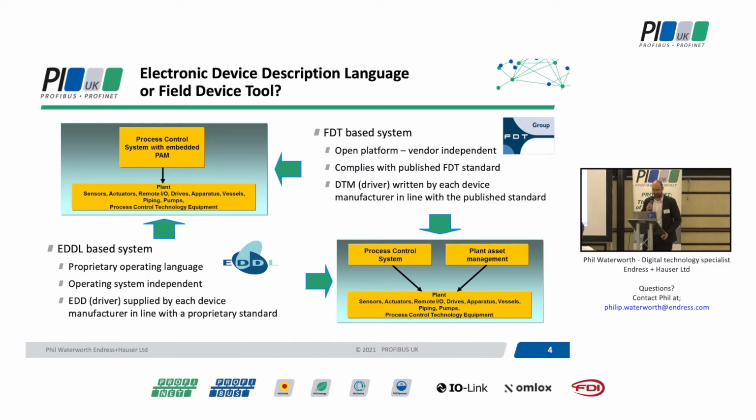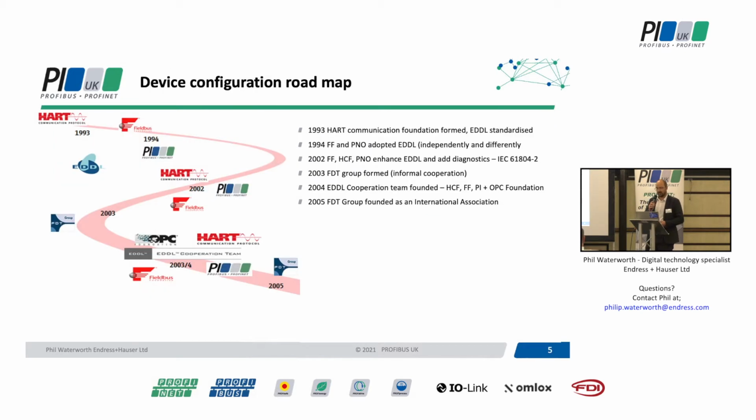So it can actually reside within your control system package that you have, or it can reside as a separate asset management tool, completely separate to your control system. And that is the case for both EDDL and FDT based packages. You can see here some of the statements that they both make. Manufacturers are required to write driver types for each of these types of software. But once they're all in there, you can communicate with pretty much anything from these tools.